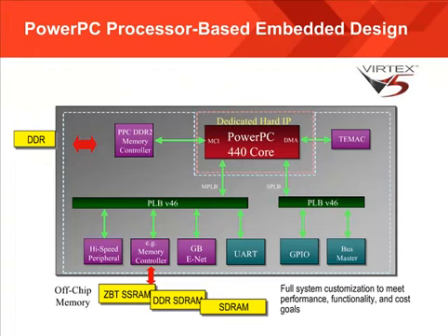In this case, the entire system, except for the PowerPC core, is built with those standard FPGA resources, so the speed will depend on the size of the entire FPGA design and the ability of the implementation tools to place and route the design optimally. In the end, the smaller the system, more likely the faster your various buses will operate. But also in the case of the PowerPC core, usually customers are running their buses at a slower clock rate than they're running the actual processor.